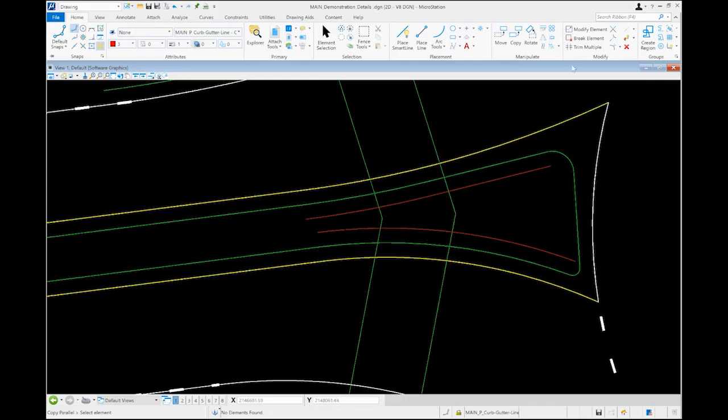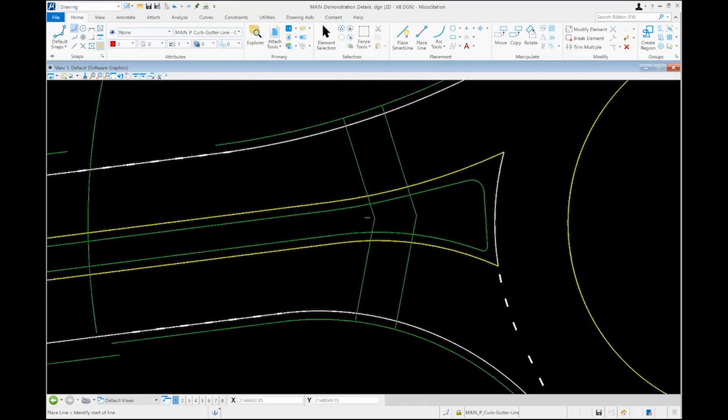dome detectable warning surfaces. For splitter islands that are a little bit narrower in width, one of the potential trade-offs is that if you had a visually impaired pedestrian that is crossing through the center of the crosswalk, there's the potential that they could sort of travel straight through the crossing and miss these angle points, miss the change in alignment. So if you have a particularly narrow crosswalk, an alternative could be to use an alignment that is straight across the overall approach as opposed to perpendicular to the individual entries and exits.